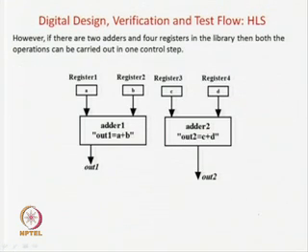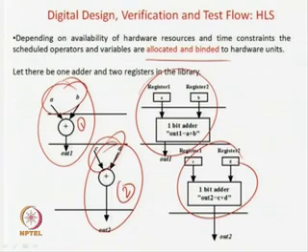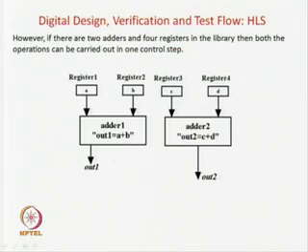In this case this is a very good looking design, because everything is done in a single stage. But you can see that there is a problem: we require more hardware here than here. In this case we require only 2 registers and 1 adder. In this case you require 2 adders and 4 registers. So, a person may not be happy with this.